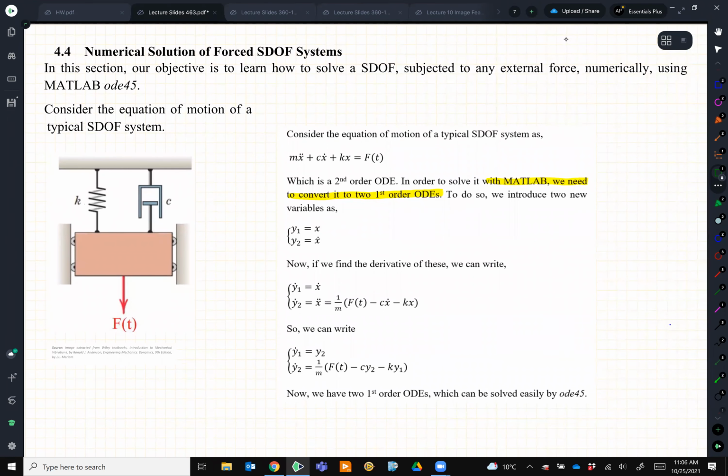this is where we say, well, so far this F(t) that we discussed was all harmonic forces. What if now we have a more general force, let's say an impulse, which happens a lot, or maybe just a static force, or any random force. Let's say the force from a road coming to a car, right? Any general force. There are two methods. One is that this F(t), we convert it to lots of sine and cosine. How can we do that?